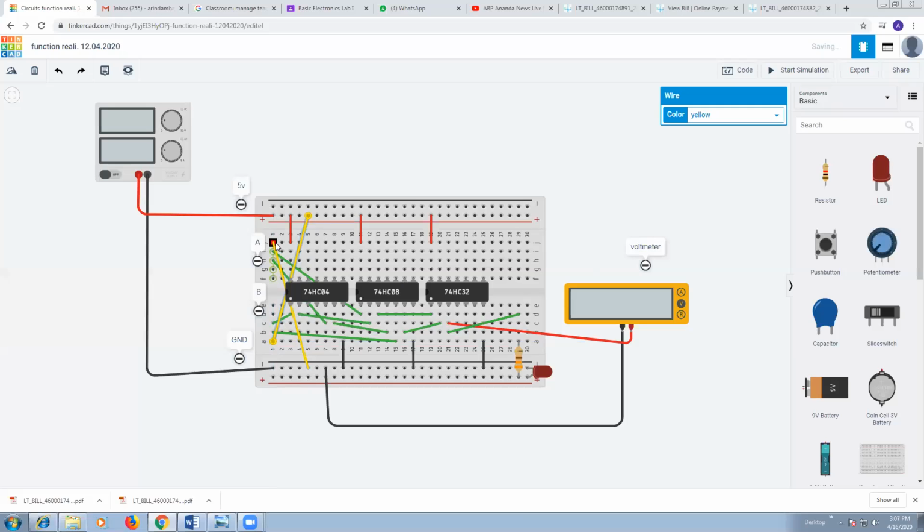If you do it the first time, then you can change these two yellow wires, which I denoted as the variables A and B. You can connect with 0 0, 0 1, 1 0 and 1 1 logical, and you can get the corresponding voltages. By transferring the red wire of the voltmeter to the suitable pin, you can measure the corresponding voltages from here, by which you can write the corresponding voltages in your lab workbook.